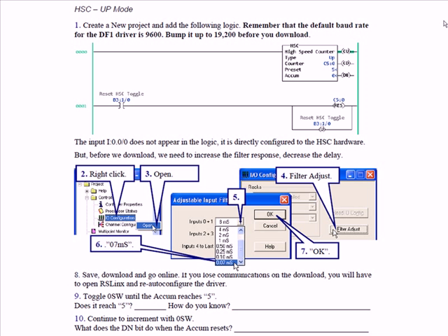Now, ordinarily you would right click on the done bit and toggle it off, but in this case we just want to reset C5:0. So to make it a one-click operation, when you right click on B31 in rung 1, it will change it to the on state, which will execute a reset for C5:0, and then it will unlatch B31:0, the bit you just toggled on. It makes it a one-step process. A nice little piece of code to remember when you need it.